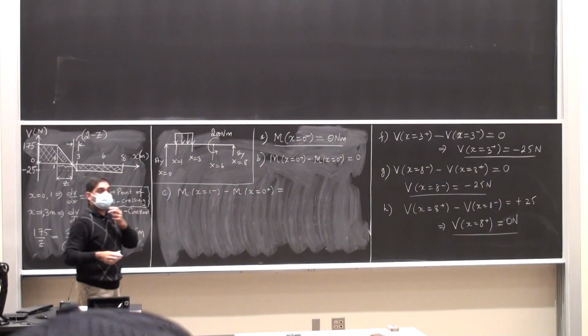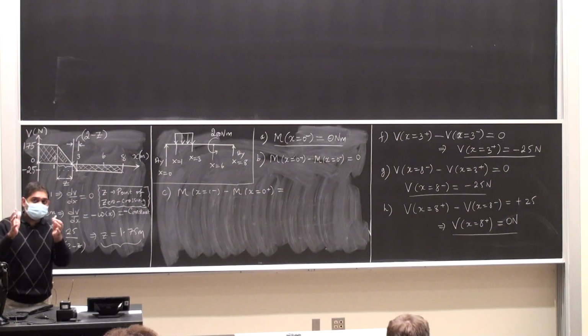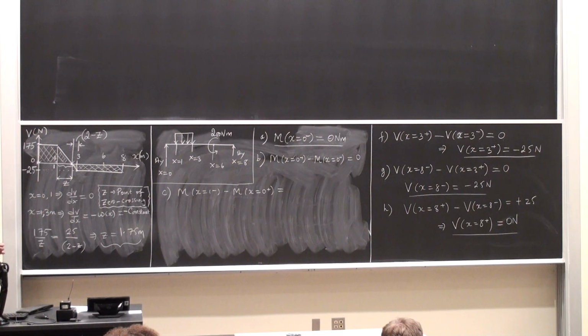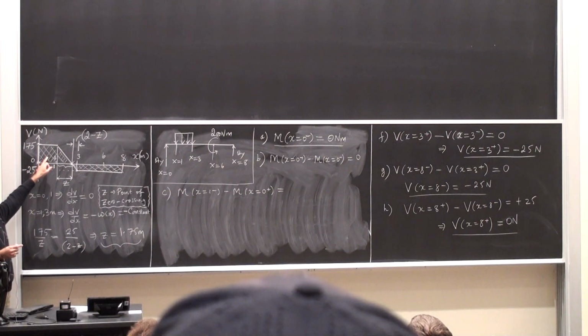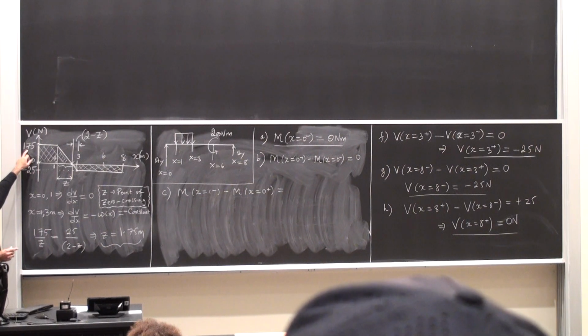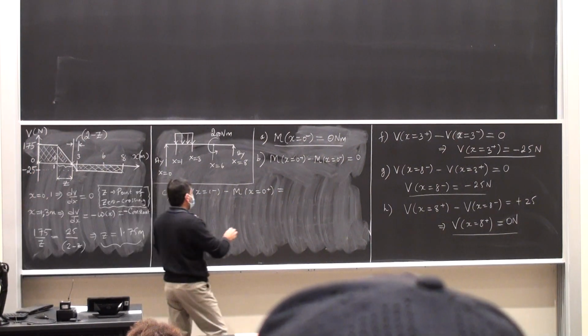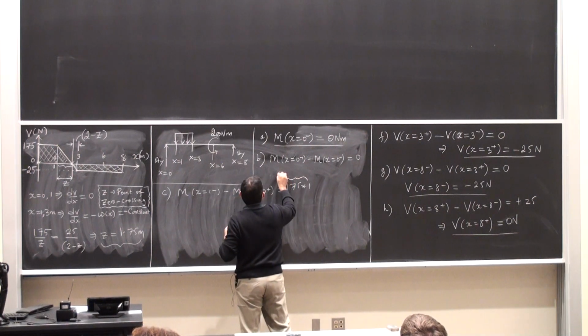What is this value equal to? The change in the bending moment diagram is equal to the area under the shear force diagram. So I have to look at the area of this first rectangular box. Watch out. Plus 175 times 1. So this is a positive quantity.